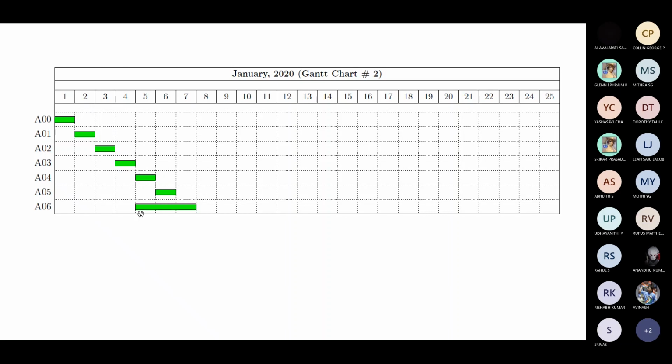So even though we plan to start the PCC laying in 1 day, if suddenly this happens, the PCC laying should not get delayed. So that's why we give 3 days instead of 2 days. So 1 day is a buffer. If this happens, that particular day will be allocated for this. If this does not happen, then we will complete it once we finish the transportation itself. So that's the power of good scheduling, or of scheduling people or planning, something like that. So that's how they generally do this.